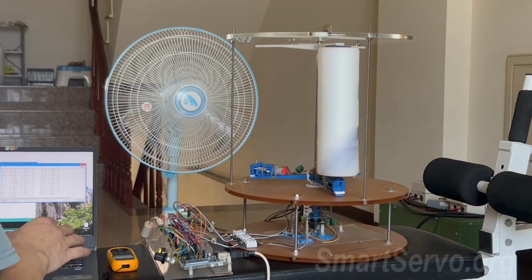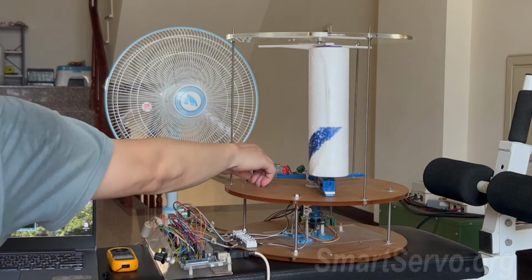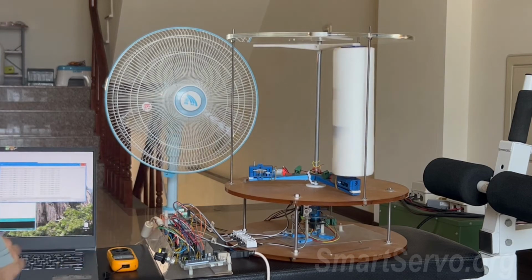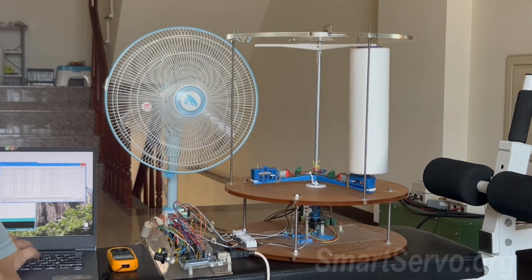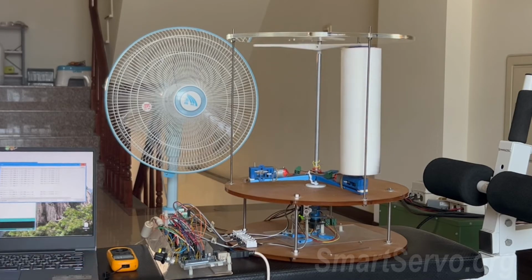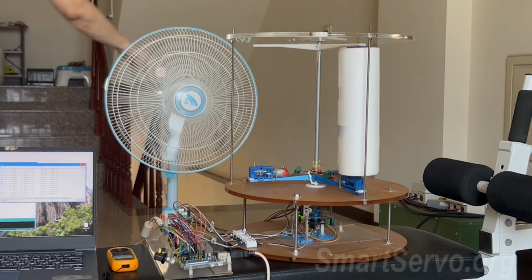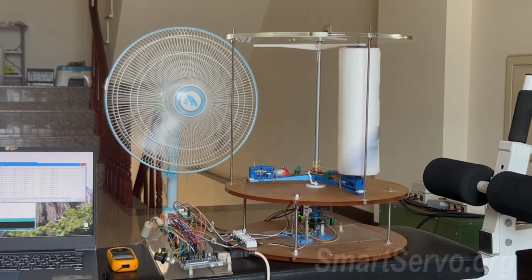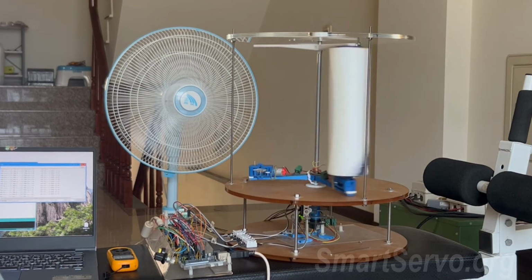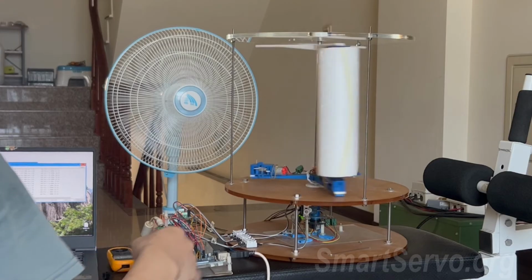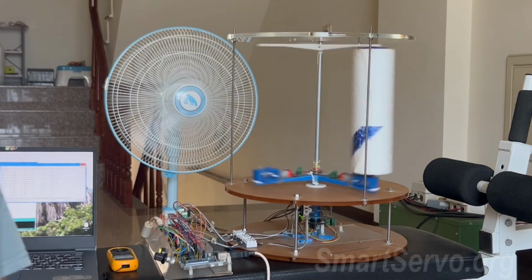Use just one rotor to see if it makes any difference. Change the direction of rotation. Conservation of angular momentum has little effect. The main shaft cannot continue to rotate. Turn on the fan again. The rotor swings violently. Therefore, the turbine is mainly affected by the Magnus effect.